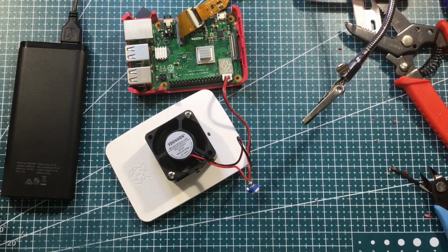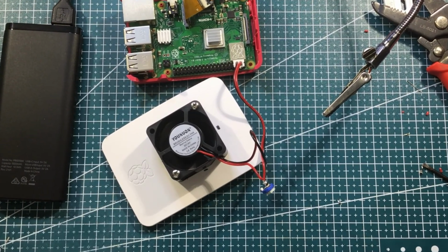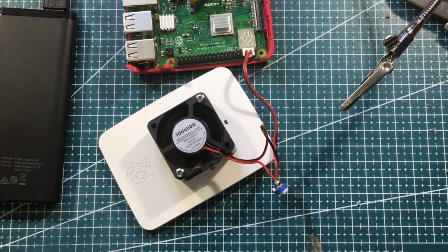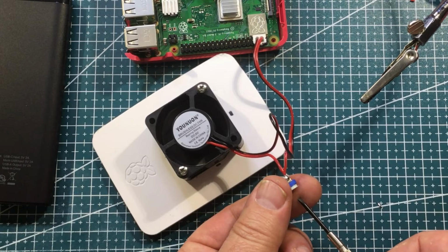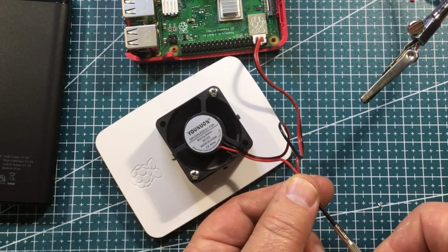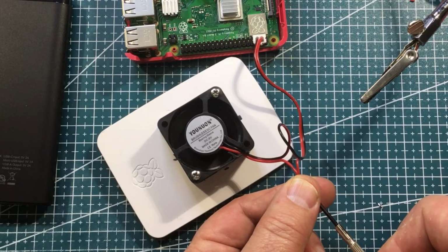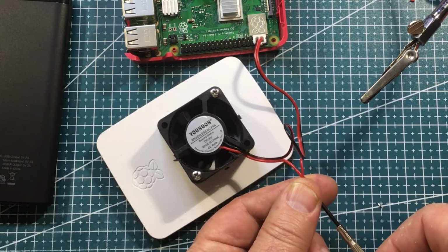Well, I seem to have a dearth of large potentiometers that have low resistance. This is a 200 ohm little pot. It's a pretty unsatisfactory one, really, but it does work. Slows the fan right down, and then maybe after half a turn or so, there it goes, it's stopped.